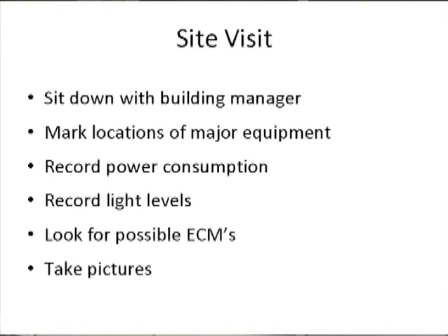But what we do differently is we actually measure the light levels in every one of the spaces, no matter how many little bitty offices we've got, and we compare them to the standards for the industry. In this case, it's called the IES. It stands for Illumination Engineering Society. They publish standards for all different kinds of spaces and all different kinds of tasks taking place in the space.